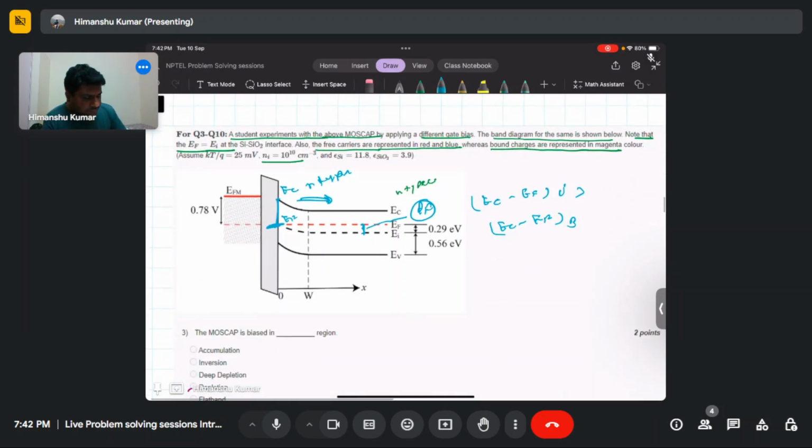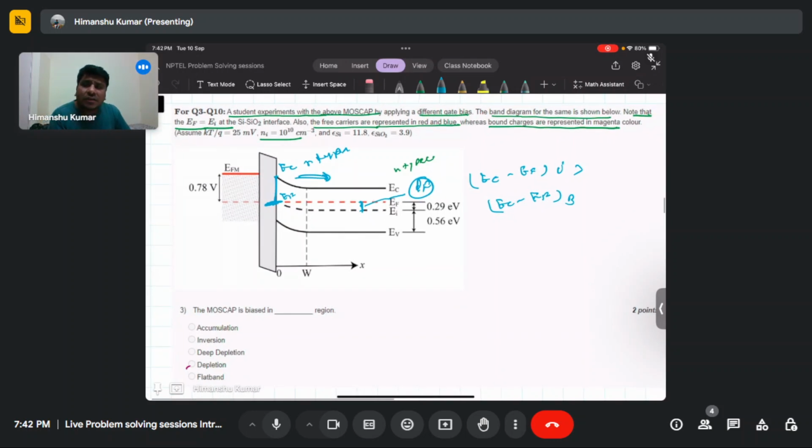This is just the threshold of the inversion layer region, because now the interface will become intrinsic, as EF becomes nearly equal to EI. The depletion is such that the interface has become completely depleted, like an intrinsic semiconductor.